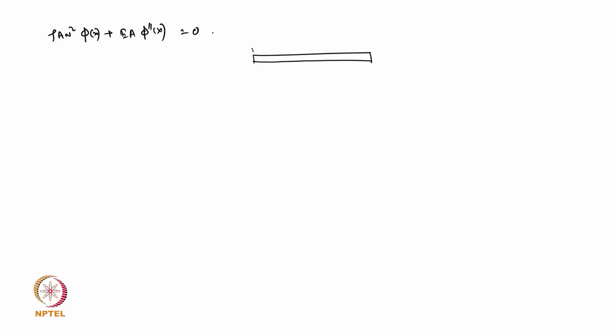So suppose you fix that bar on one side and you let the other side go. What type of boundary condition should it have? If this is 0, this is L, so you can say that u of 0 comma t, please be careful, 0 comma t, because we are just specifying the boundary condition at the 0 side, which is valid for all the time steps. That is not getting changed. Fixed remains fixed.